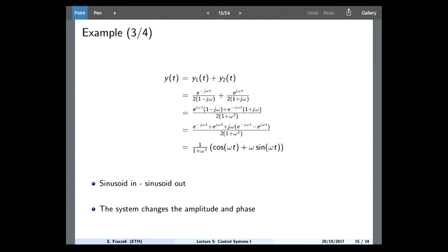You see that the temperature will not change that much, just because the temperature in your cabin will not change so quickly as you are switching the heater on and off. When my input is very high frequency, which means omega is large, the amplitude of your response becomes closer and closer to 0.